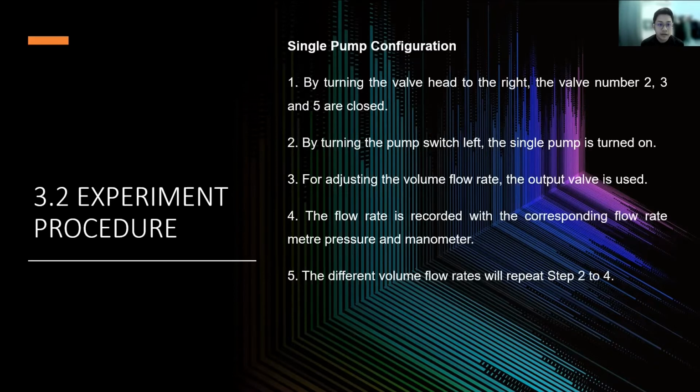The next procedure is single pump configuration. The first step is by turning the valve handle to the right. Valves number 2, 3, and 5 are closed.